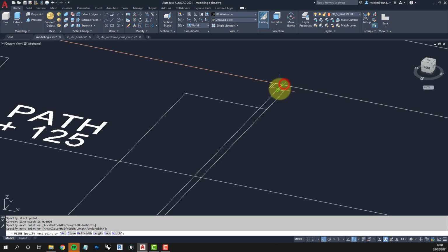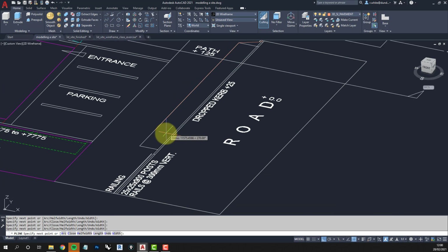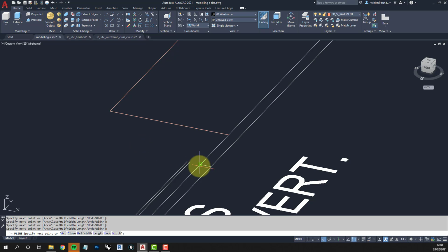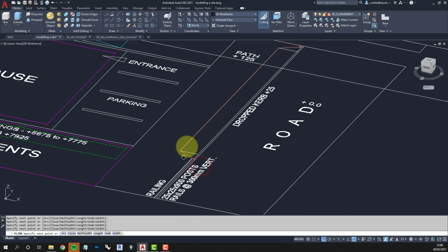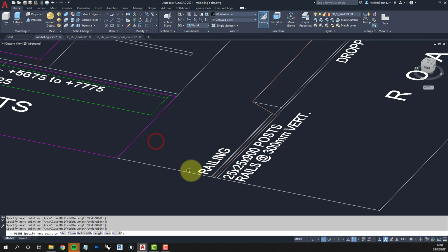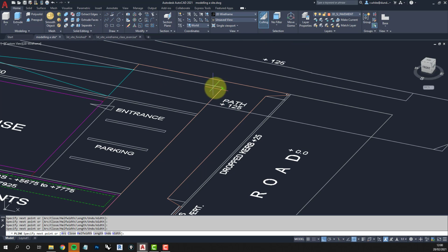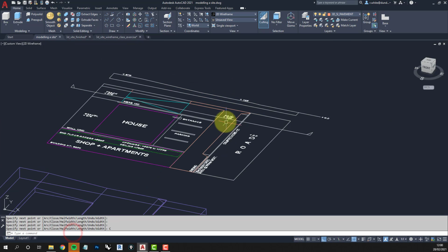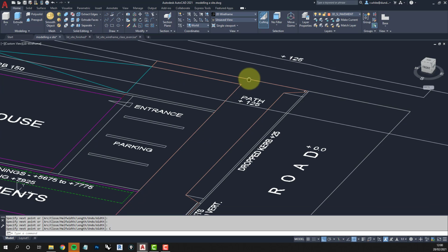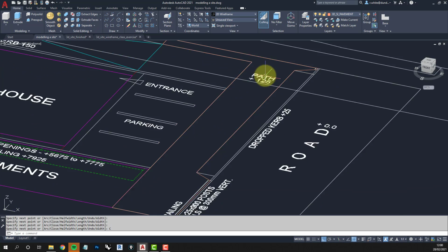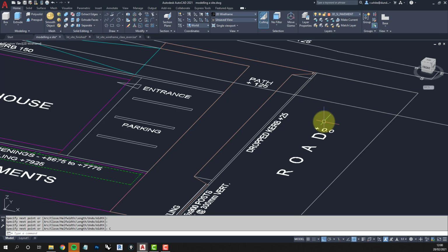So we come to the top of the curb there. To this point is where the transition starts, and then we've got that triangular sloping bit, which is trickier to define. So we'll come to here, along to this side, back to the corner of the transition, to the end of the curb, over to the building, and we can just run right the way along now to this end point and then close the shape. Okay, so that needs to be 125 millimeters above the road.